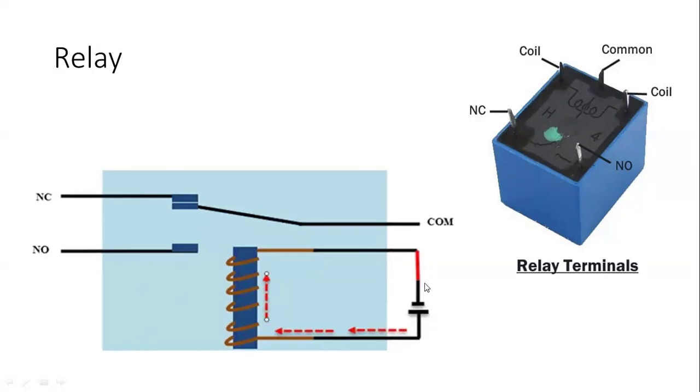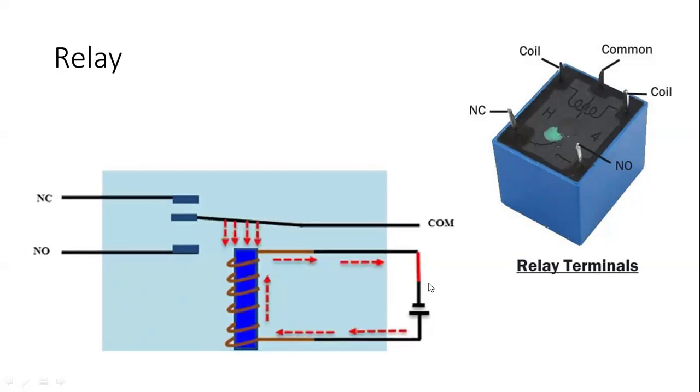And this one is the battery and the switch. We can mount them over here to check it out. But in place of that battery and switch, we have to use an Arduino digital output. Like from the digital output, we have turned on the buzzer, the motor, and the 3 LED sequence also. That digital output of the Arduino we have to connect here with coil 1 and coil 2. With the help of that, we can make it on and off.